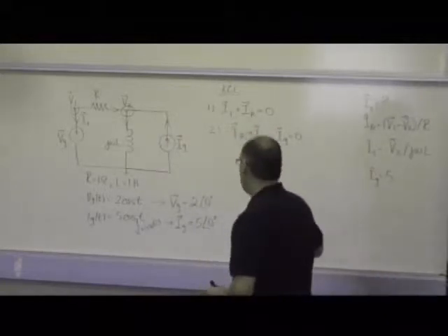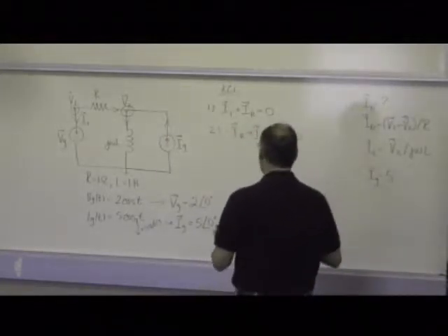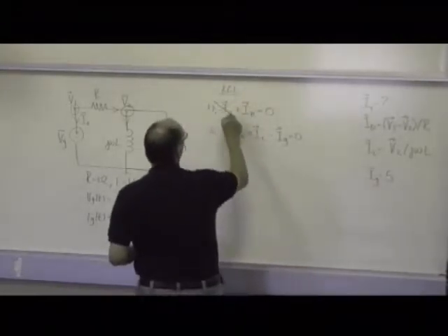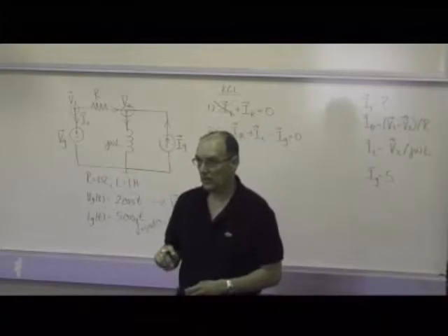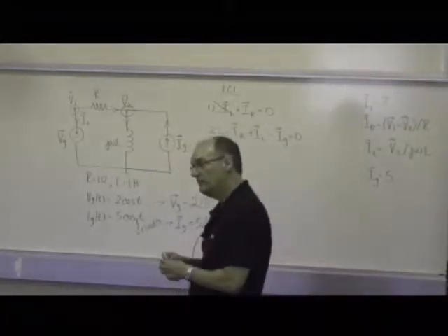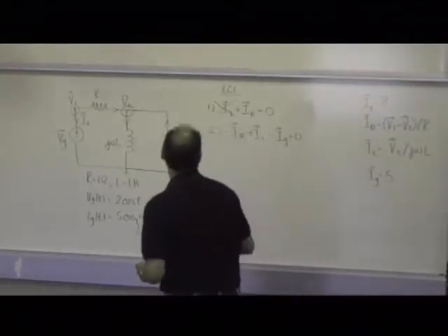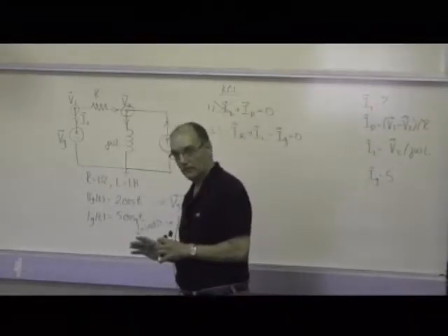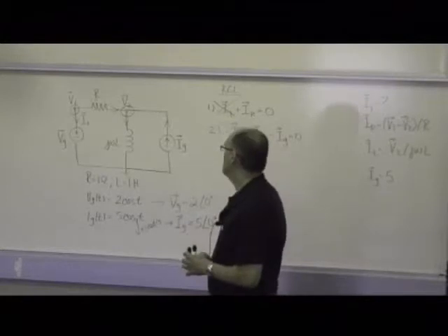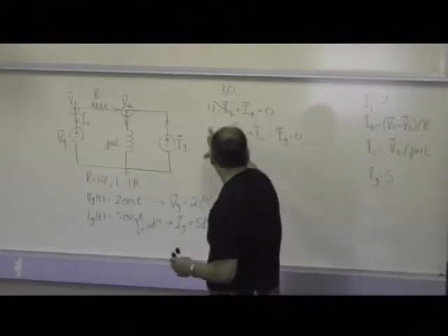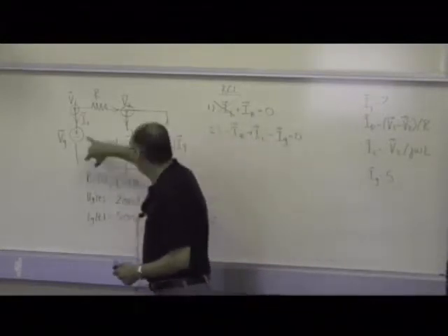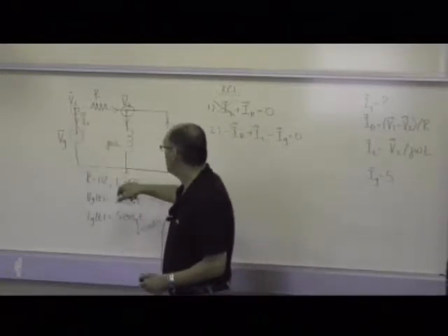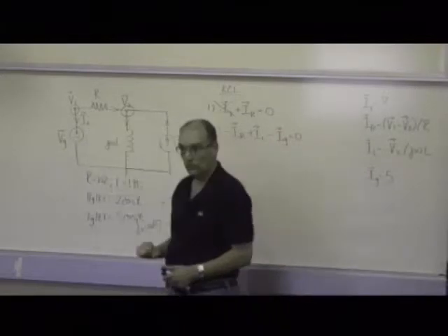Now, whenever that happens, and it will every time you have a voltage source, you lose the equation where that quantity shows up. And you have to come up with a different one, a so-called compensated equation, where you rely on something other than Kirchhoff's current law. Now, with voltage sources, you always know something that hasn't actually been used. In particular, because you have this voltage source sitting here between node 1 and the reference node, you could say that V1 equals Vg.